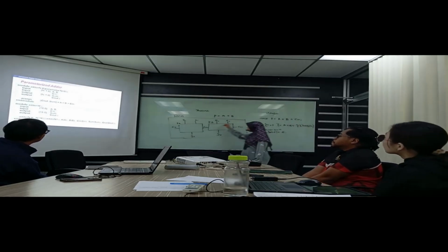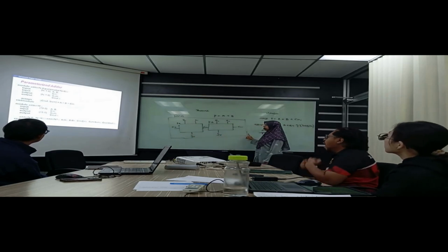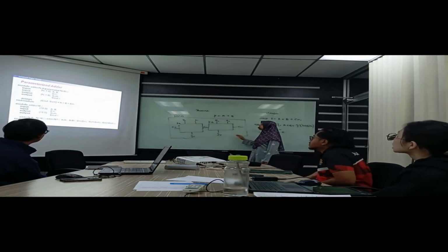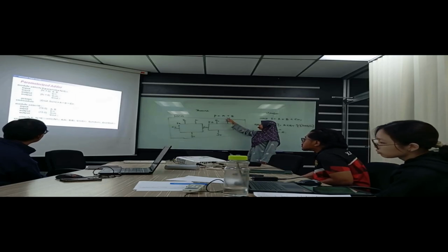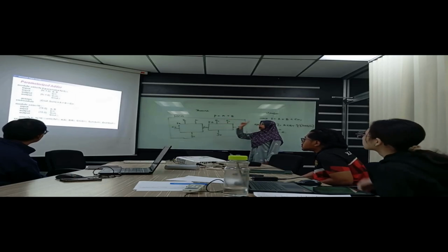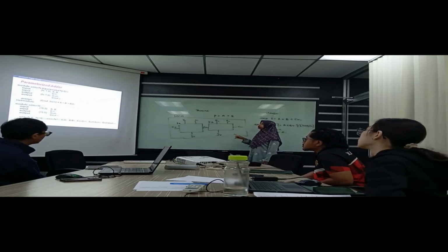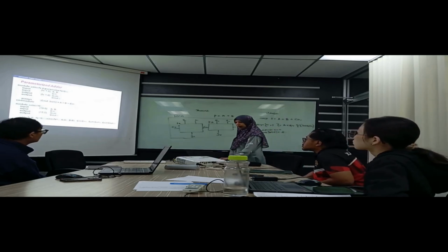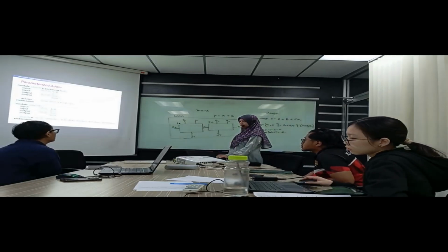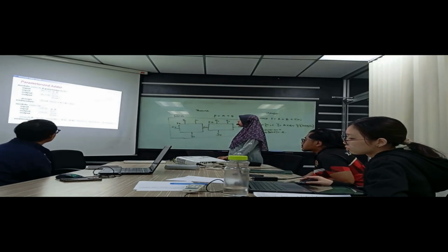You have created the 4-bit adder, and it is a waste if you just throw away that design. Why not just reuse it? The adder design with 4-bit, but you use the parameterization feature in Verilog to change the value to 16-bit. You are allowed to do that. Let's say in this case it is 8-bit, but now you just call this design back and change the bit value.